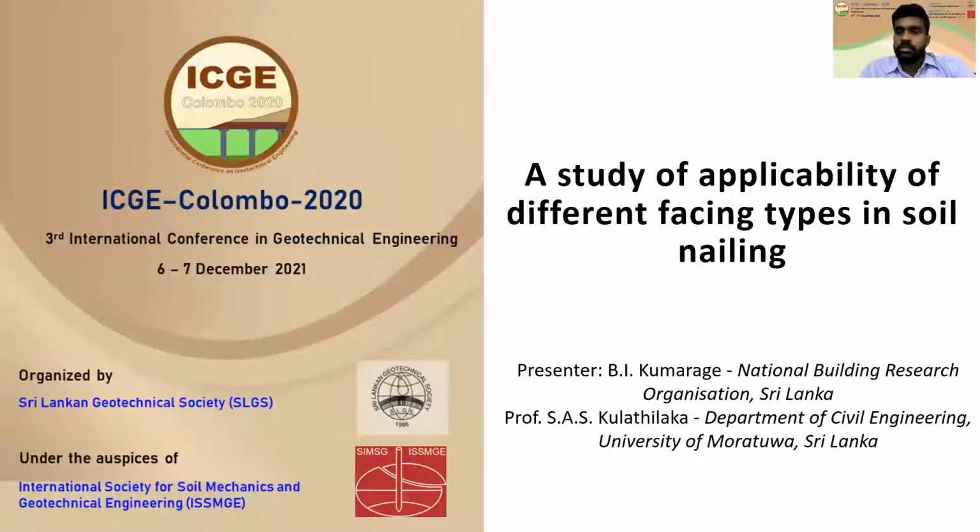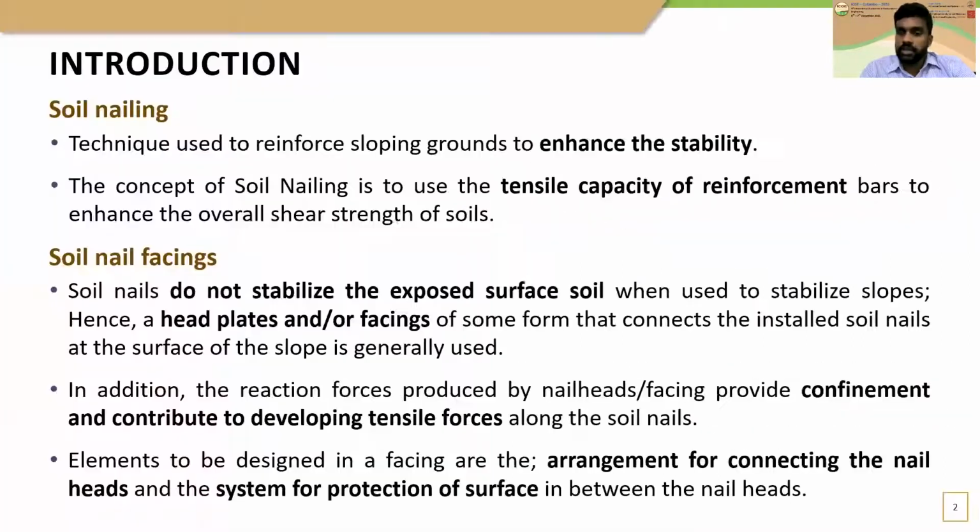A study of applicability of different facing types in soil nailing. I am Kumarage from NBRO. Soil nailing is a technique used to enhance the stability of sloping grounds. The concept is to use the tensile capacity of rebar to enhance overall shear strength of soil.